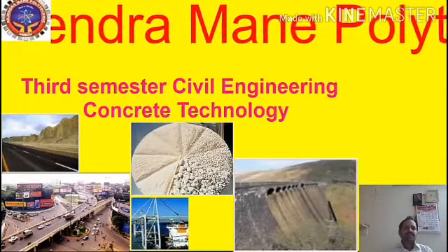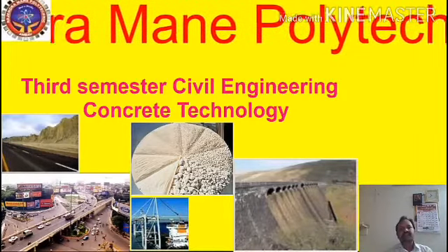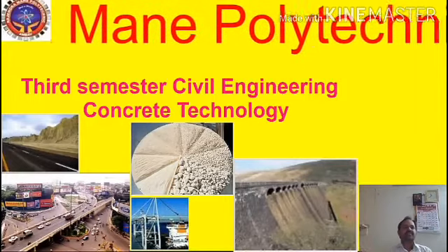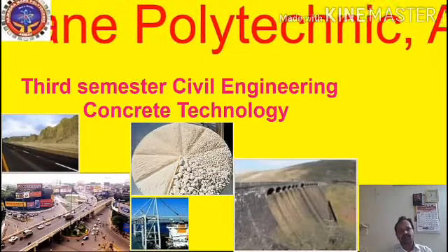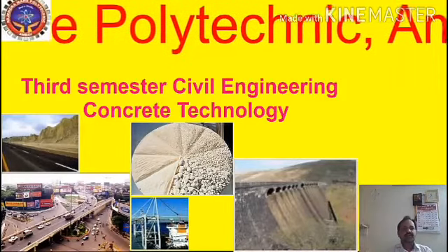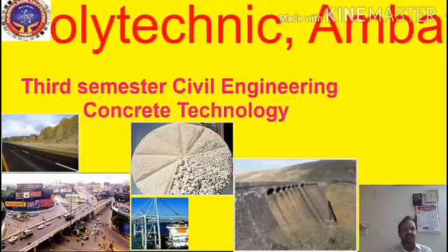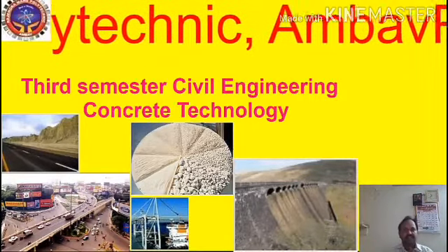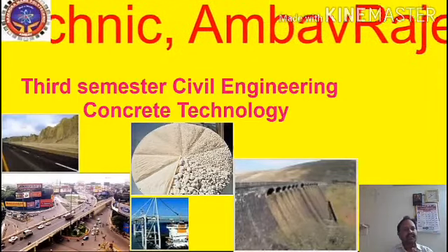In actual construction dealing with cement, mortar or concrete, a certain time is required for mixing, transporting and placing. During this time, cement paste, mortar or concrete should be in plastic condition. The time interval for which the cement products remain in plastic condition is known as the setting time.